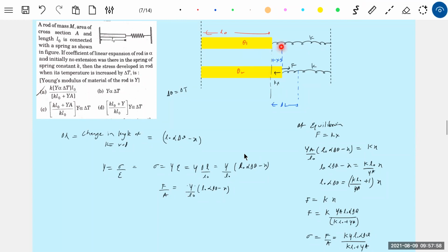I think it all revolves around this diagram. I feel like everything revolves around this diagram. Somehow the student can get this diagram and write this equation. What actually goes on here? The rod wants to expand, and the spring will oppose it. Definitely, the rod is not permitted to expand freely. So the total elongation of the rod should be less than the free thermal expansion. This is the background. If it is there, then okay, fine, you can manage.